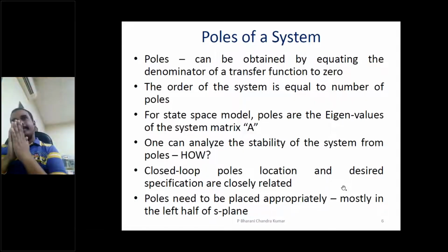Yeah, that's what you are saying, mainly the dominant pole itself. And that depends upon, suppose you want the pole to be at minus 1000, but your poles are at minus 12 and minus 1. Suppose if you want the poles to be placed at minus 1000 and minus 2000, then you have to control both the poles. Okay, sir. Thank you.